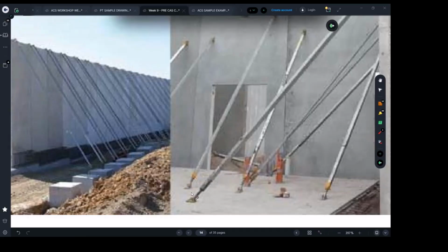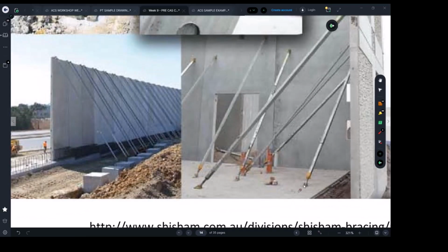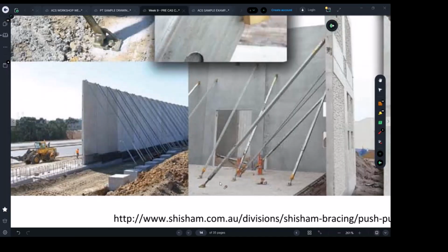You need to be very careful: if the architect needed a special concrete finish, then it won't be acceptable to have many voids there. Sometimes they will have a covering, like special paint or special tiles, then all this can be patched and you can cover them up. So it depends on architecturally what's the last finish they want to achieve. And if this process should be more economic, you don't need to allow for those temporary props.